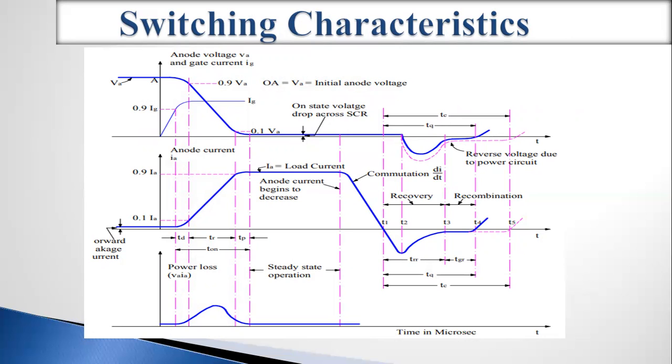As you can see here, these are T1, T2, T3. This is the reverse recovery time, and this, from T3 to T4, is the gate recovery time. So this is all about the concept of the dynamic characteristic, or switching characteristic, of the SCR. Thank you so much.